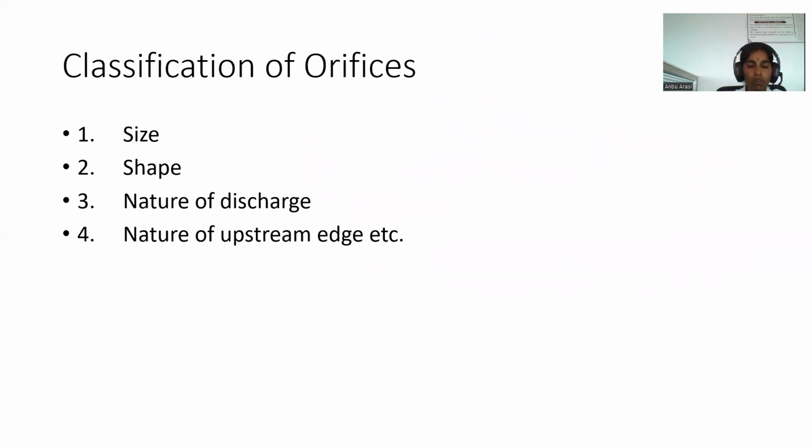Classification of orifices. According to size, it is divided into small orifice and large orifice. Based on the shape: rectangular orifice, circular orifice, and triangular orifice. Based on the nature of discharge: freely discharged and partially submerged discharge.